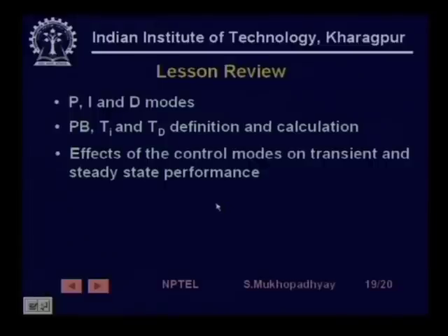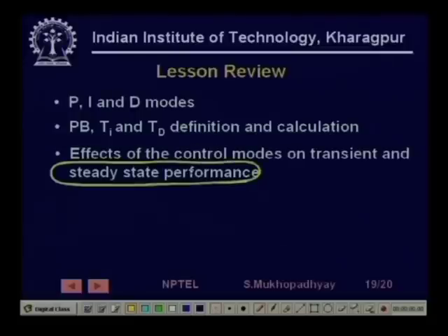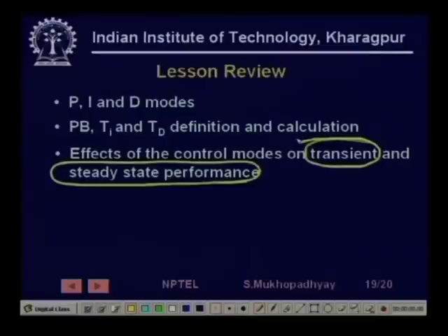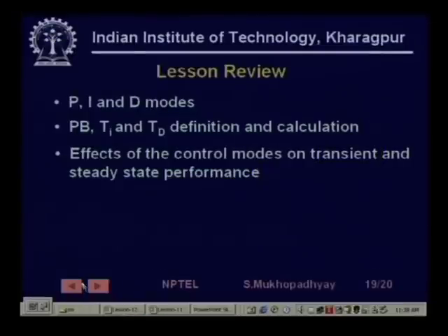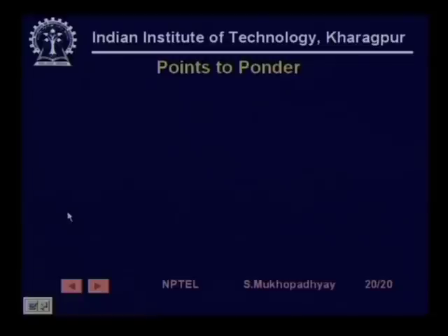For example, we have seen that the integral control mode can cause integral wind up. Similarly, we have seen that the derivative control mode can give you a lot of noisy performance if you have sensor noise. So, some effects of these control modes on performance are discussed. These problems with D and I modes we have discussed, and finally, we have discussed also a digital realization.